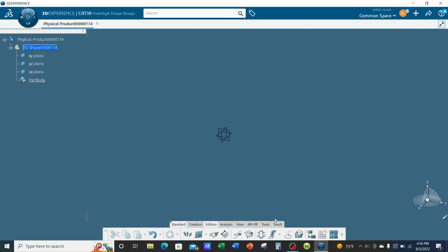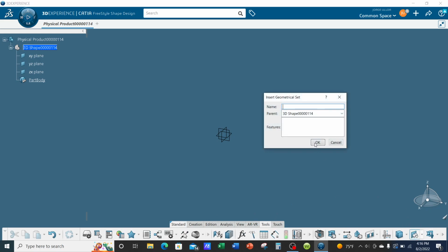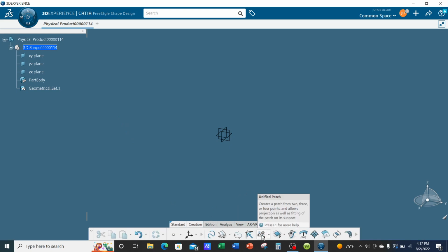Alright, so let's start by creating a geometric set. And OK. So we'll place our surfaces in this geometric set. And let's start by creating a patch. So let's go to Creation, Patch.